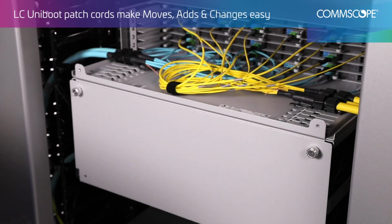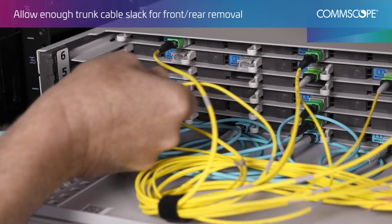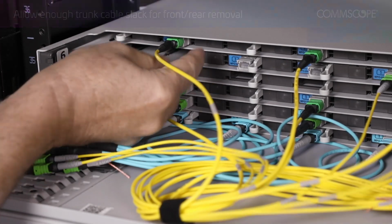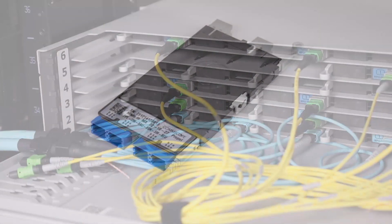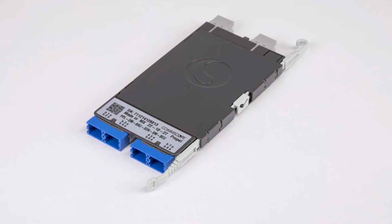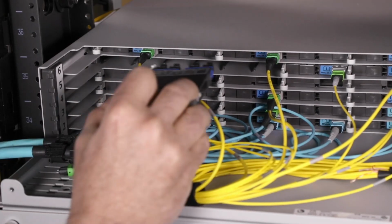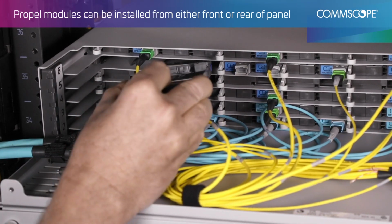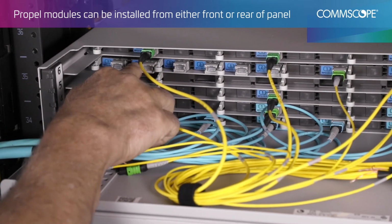Disconnect the MPO 8 trunk connectors from the rear of the modules. Remove the modules by pulling on the pull arm and sliding them backwards or forward, depending on your installation. Now we can install our MPO to SN module, which enables us to increase fiber count within the same panel. Insert the SN modules onto the blade. Align the rails on the blade with the slots on the bottom of the module and guide it into position until it locks into place.